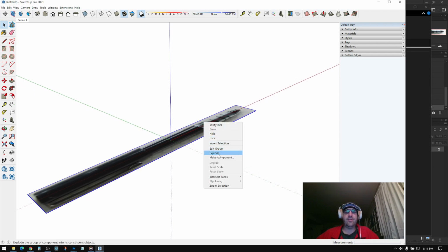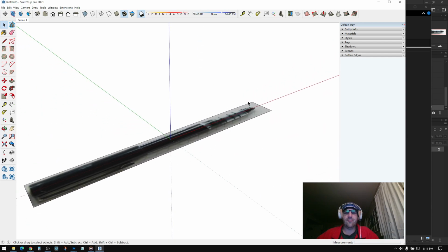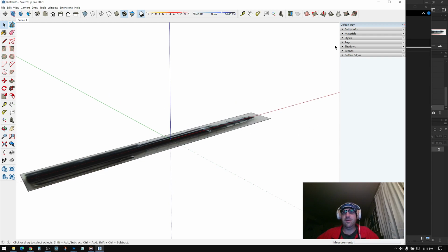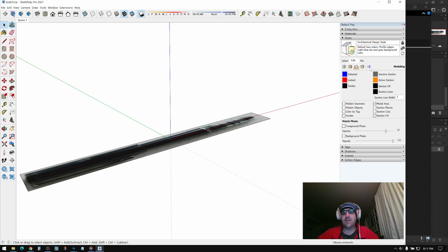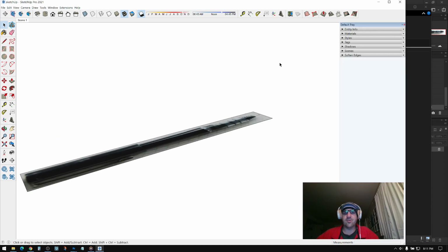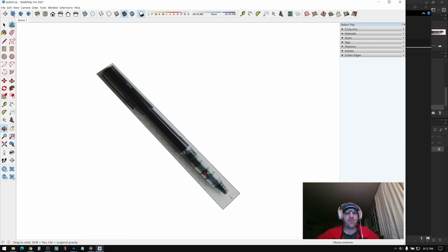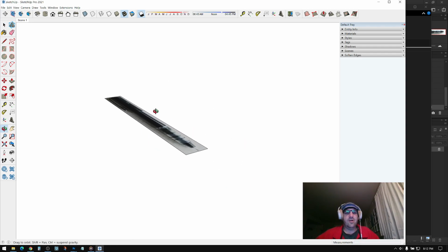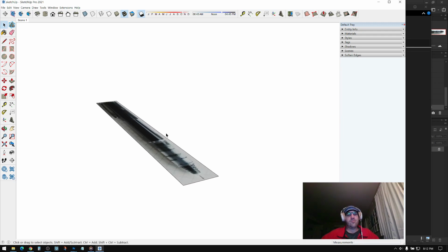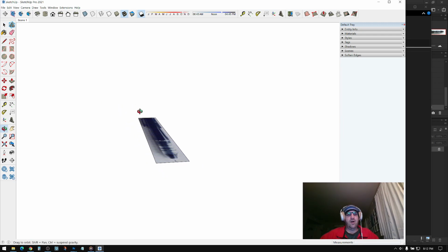So now I can explode that group because I'm done scaling and centering it. Now I can start modeling it, and I'm just going to turn off this axis too. I'll go to Style, Window, Edit, and then the last one, I can turn off Model Axis, just to clear up the screen. I already know it's in the right spot to start my modeling process.